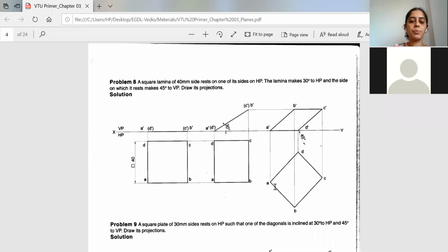After getting this edge, you know that all the sides will be perpendicular in the square. So you got this point; name this as A and D. From here, keeping the protractor at point D, take 90° exactly. Keeping the protractor at point A, take 90° exactly. Then you measure 40 mm and cut an arc on this 90° line. Similarly, measure 40 mm and cut an arc. You will get the point B. So then you got the points A, B, C and D. So you will join A to B, B to C, C to D and D to A.